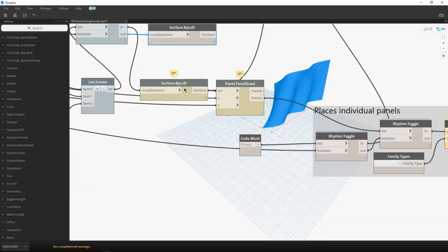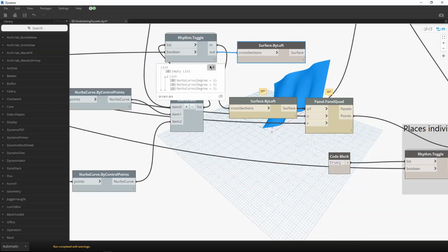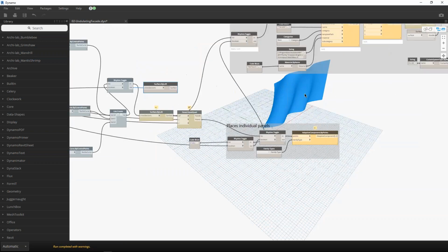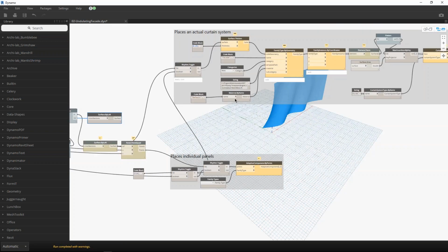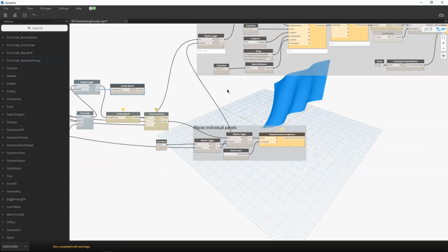These ones are yellow because I am actually forcing an error on purpose. That way it won't bake stuff into Revit and start turning for a while. The minute you push geometry into Revit, it has to create it, so it takes a bit. So I'm actually forcing that error on purpose. So don't get too scared when you see yellow errors. It's not the worst thing in the world all the time.